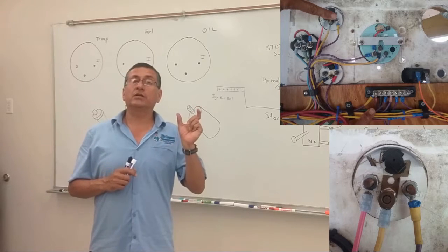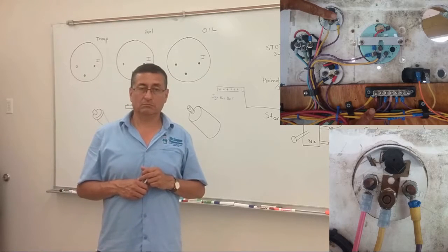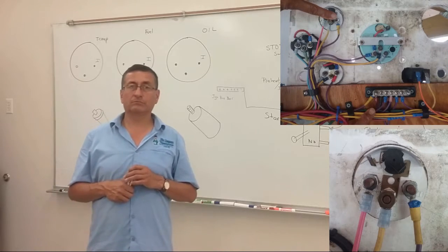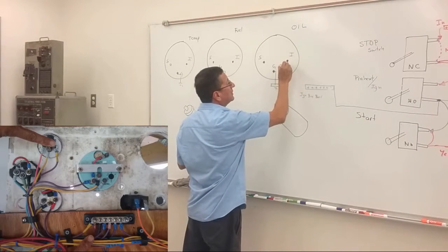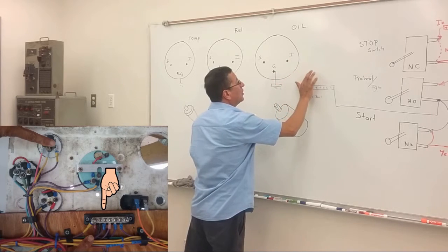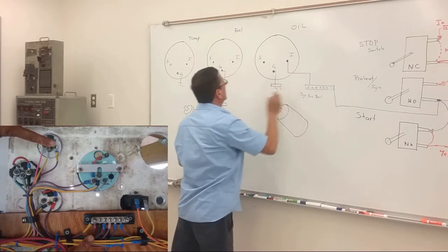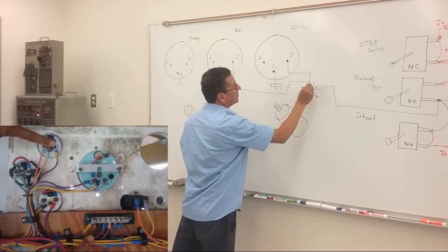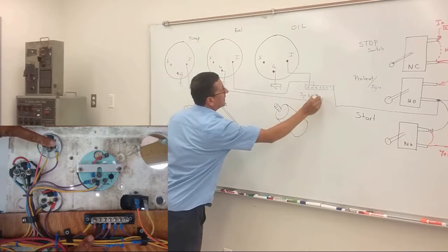Remember, in order to send the signal to the gauge, we are going to use the sensors. In this particular case, we are going to use the oil pressure sensor, and all the ignition positions shall be connected through the ignition bus bar. Normally this cable color is purple. And this one is connected to the ignition bus bar. And this one is connected to the ignition bus bar.